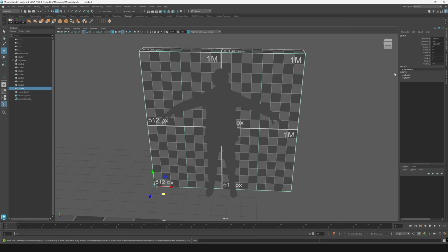If it feels maybe a little too wide, then let's just go right here to the sides and go to that poly bevel that we had just put on there. And let's change the fraction to maybe 0.45. So if it's good, maybe 0.4. Just, you know, kind of eyeball it and feel. If not, if you really want to see size-wise, you can always measure your doorways to try and make things a little bit easier.